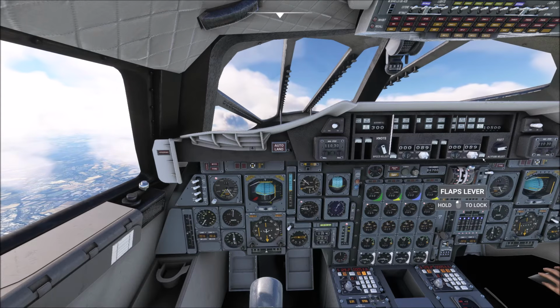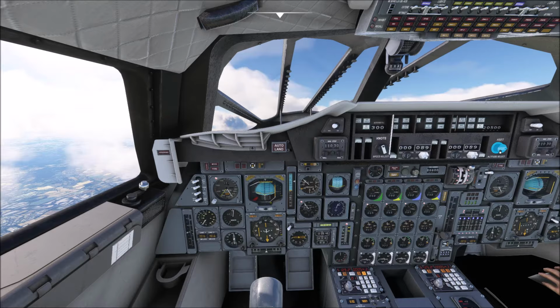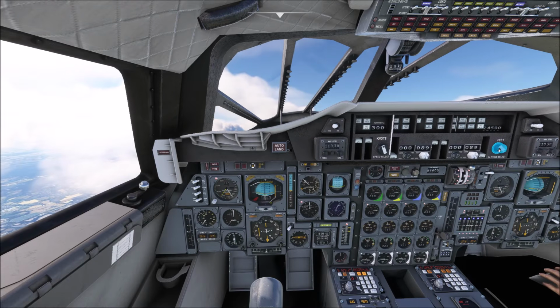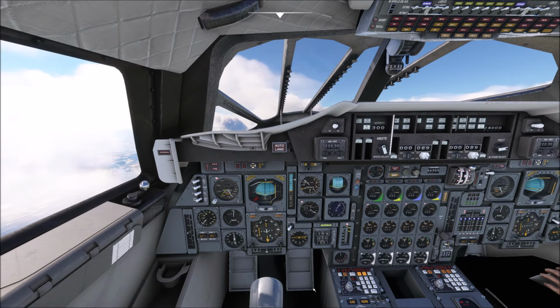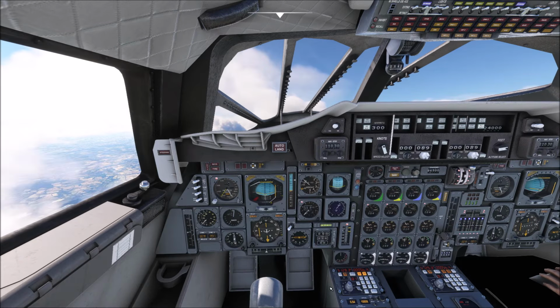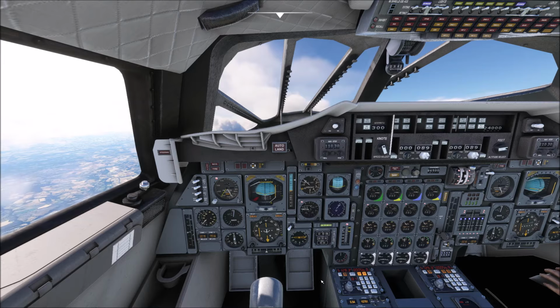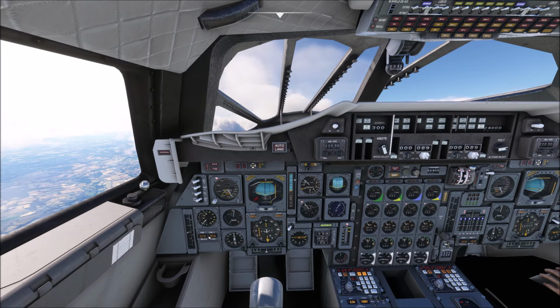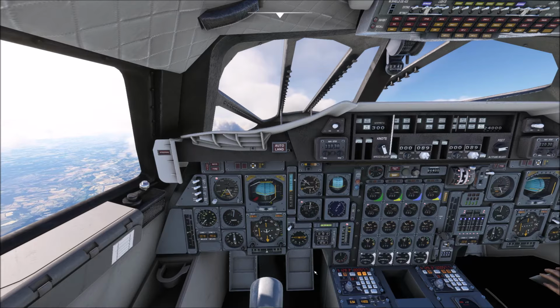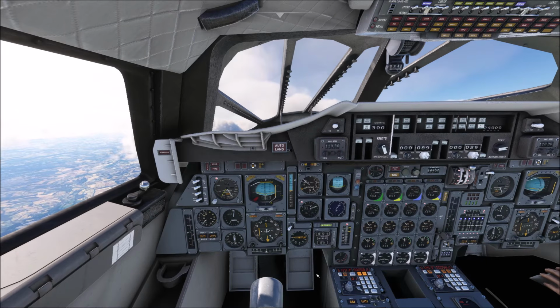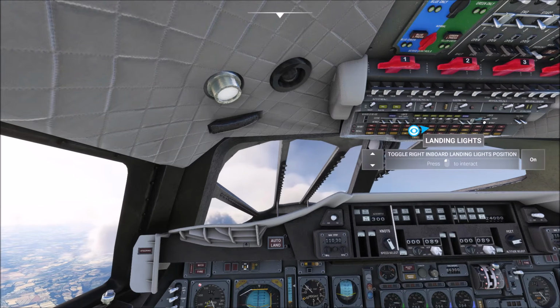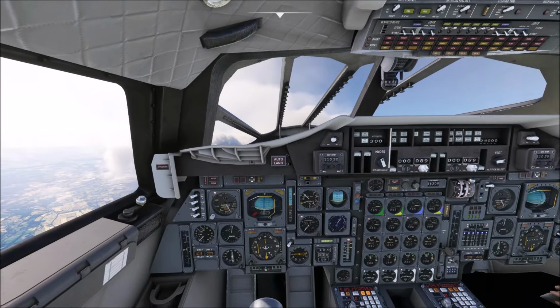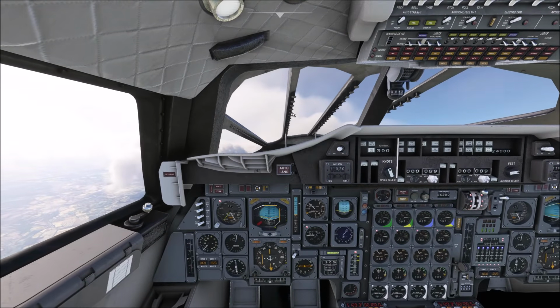Coming up to 10,000 feet now. We're going to push that up now, 20,000. That's the altitude we want. We leave it on altitude require. Concorde will balance itself and take care of everything. Still tracking the INS, everything looking good. 10,000 feet now, so we can shut off the landing lights. And we're steadying the climb.